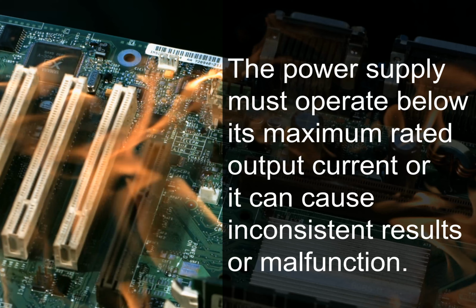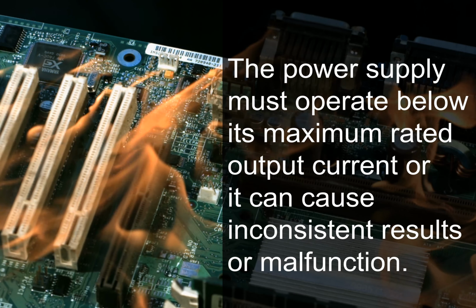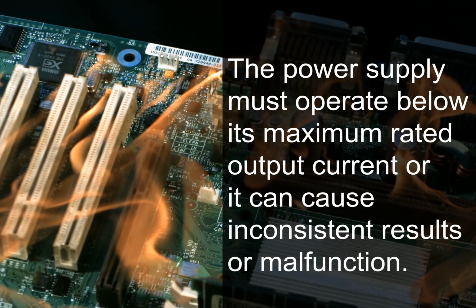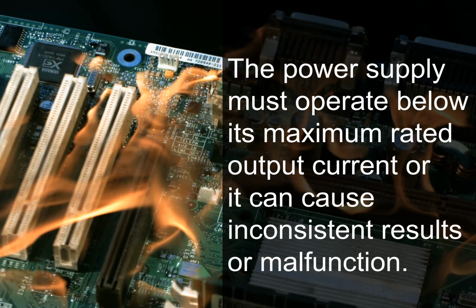Along with the above considerations, the power supply must operate below its maximum rated output current. Loads drawing more current than the adapter is rated for can cause inconsistent results or device malfunction. Overloading the converter can lead to overheating and ultimate failure, potentially causing a fire hazard or damaging the load itself.